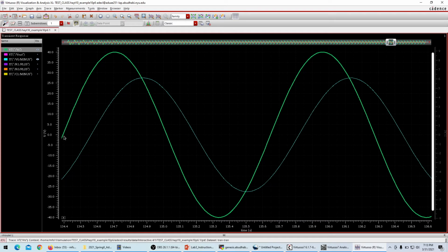Now we know that this half wave represents 180 degrees, right? And then half of it, which is at the middle of this one, represents 90 degrees. The 90 degrees is nearly 1, 2, and 3 grid squares. So 3 grid squares represent 90 degrees. If it's in the middle, then it would represent 45 degrees. But as we see, this wave is not passing exactly in the middle, it is a little bit ahead, which is kind of 5 degrees, telling us that there's a 50-degree phase shift between the two signals.